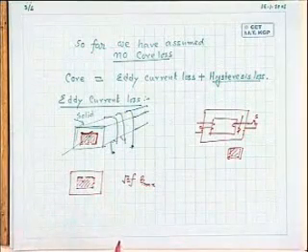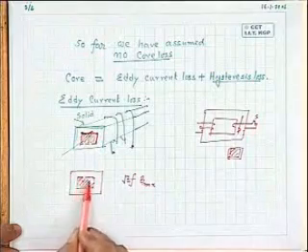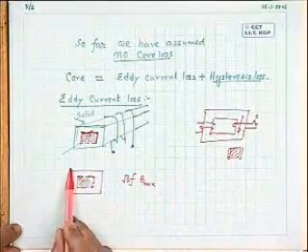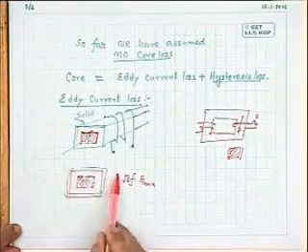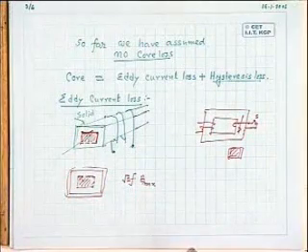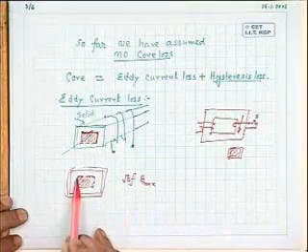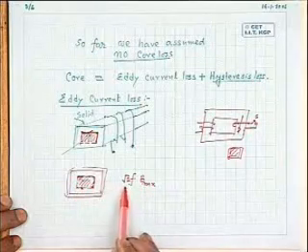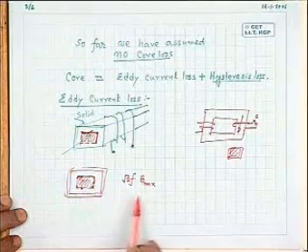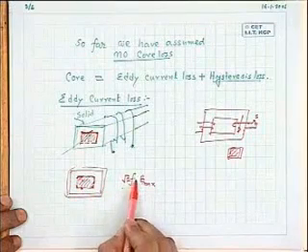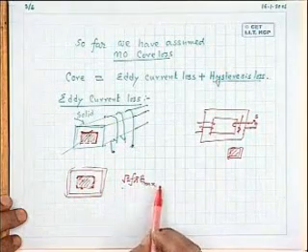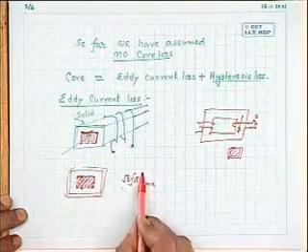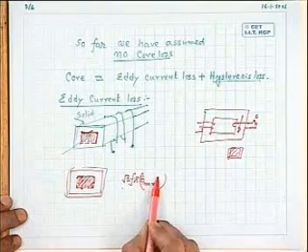How much flux is linking this particular coil which I am considering? It is the flux density into this area. In case of all the secondary turns, all the turns are wound wrapping over the whole area of the secondary. So it is B max into some constant area. But if you consider any imaginary coil inside this one, a closed path, the induced voltage in that single turn will be root 2 pi F B max into this area, the flux.